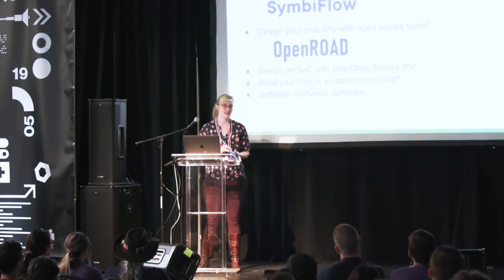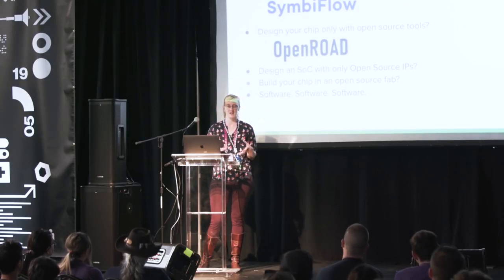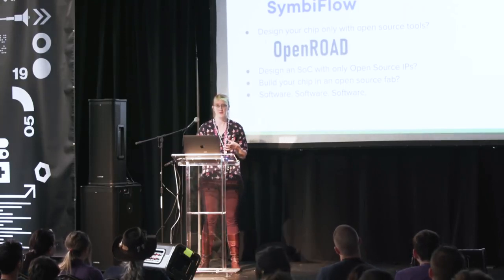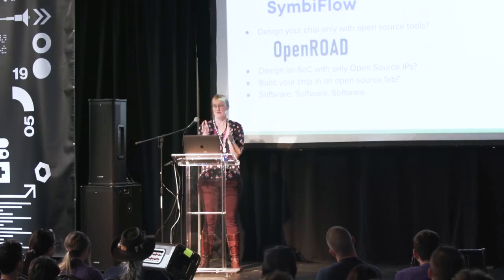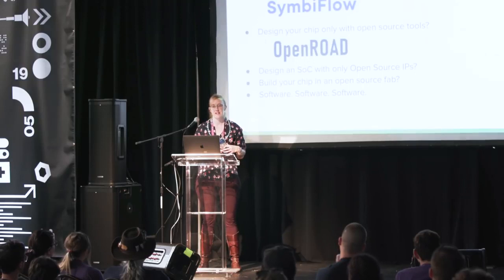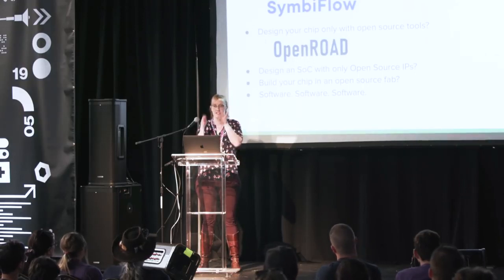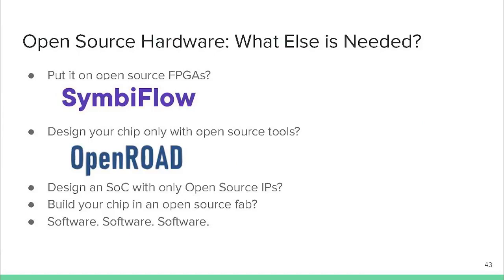There's also a problem I encounter with designing your chip itself with only open source tools. If you take your logic, the thing you'll find when you go to look at the repo for this SoC, this FPGA, there's a bunch of code there, and that has to finally get translated down to little rectangles for the stencil in the factory. And those tools are ridiculously expensive and kind of awful, because nobody uses them because they're expensive, so they don't have any incentive to make them better. So I was really excited to hear yesterday about this OpenROAD project, which is trying to solve that problem in the open source. Come up with a full tool chain from Verilog to GDS.